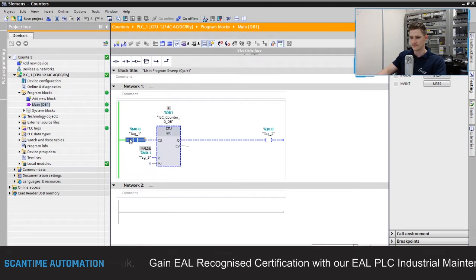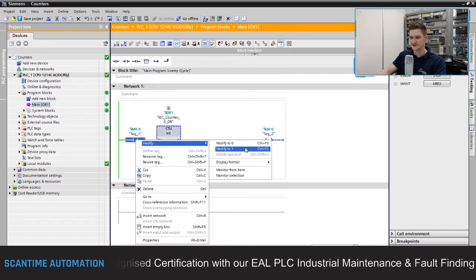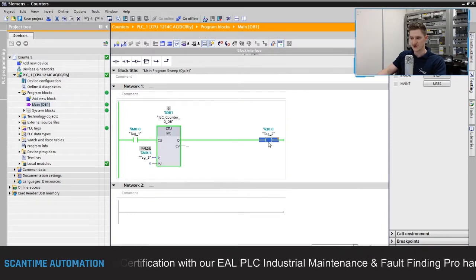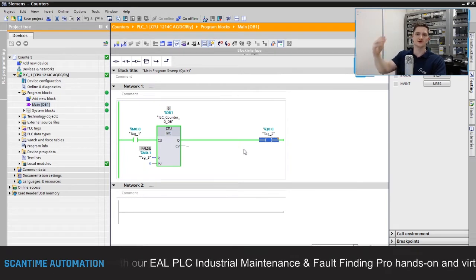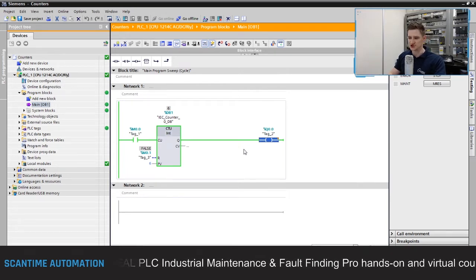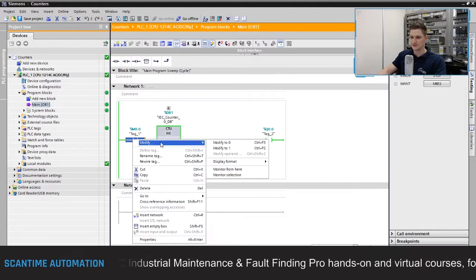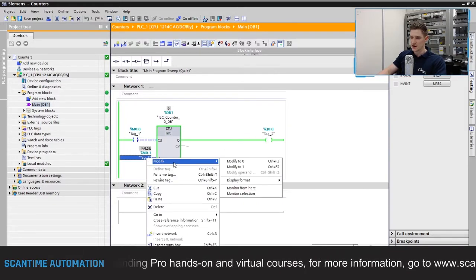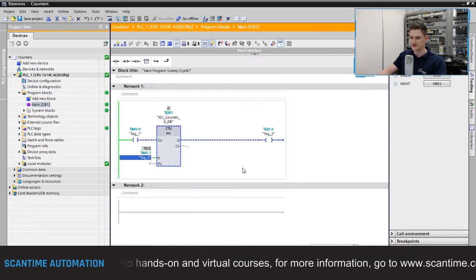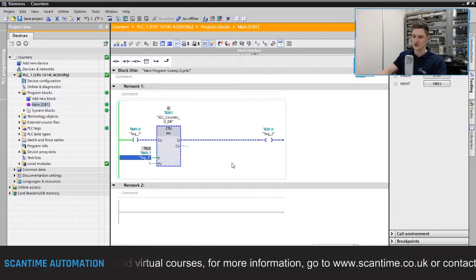4. 5. And then finally, when it hits the value 6, that's when the output coil turns on. And then that tells us that we've completed our count, and then it can proceed to do whatever it needs to do next. When the input signal turns off, we then may want to reset the counter, and all I'll do here is trigger the reset, and what that does is it resets my counter back to 0, ready to start counting to 6 again.